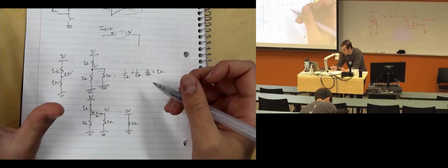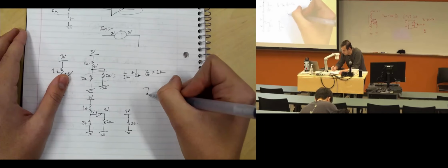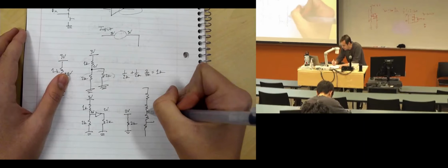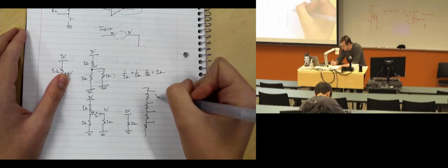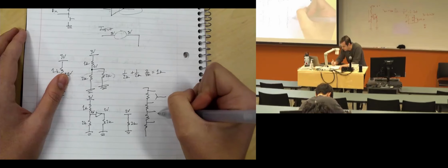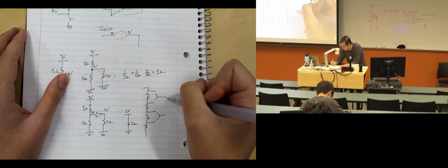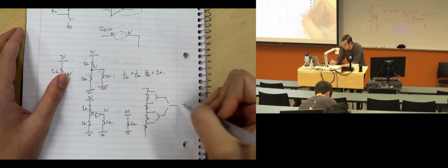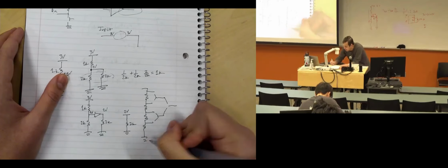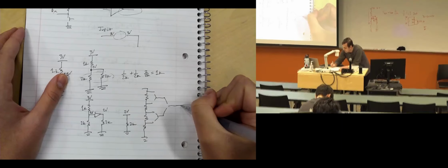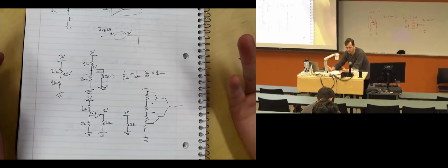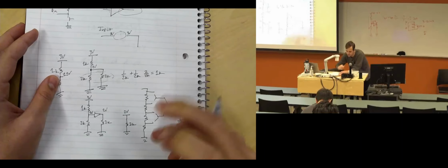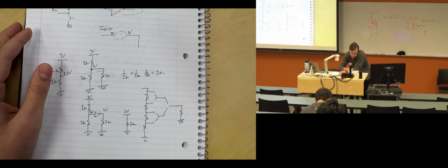How those work is a series of voltage dividers with a bunch of switches between these. This doesn't have to make sense right now, but it's a voltage divider with a bunch of switches. And you're going to use that voltage for something, so you're going to put a load onto the output of this DAC. Otherwise, you wouldn't have any purpose for it.